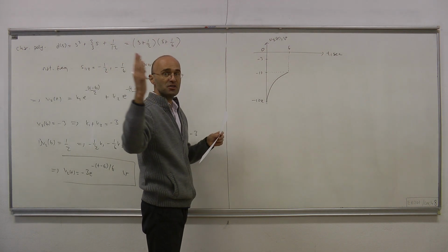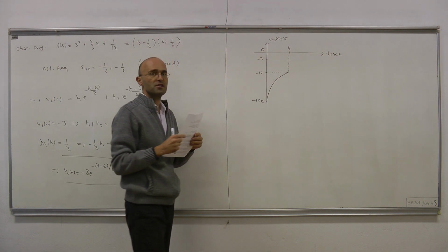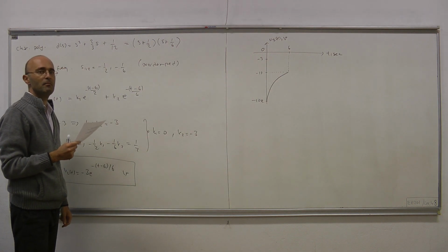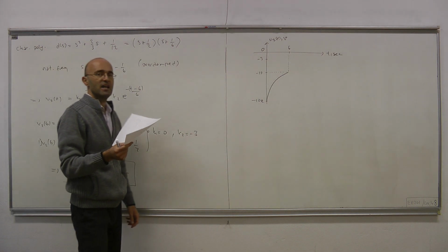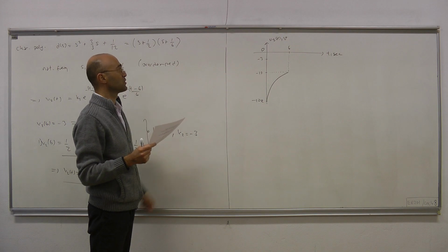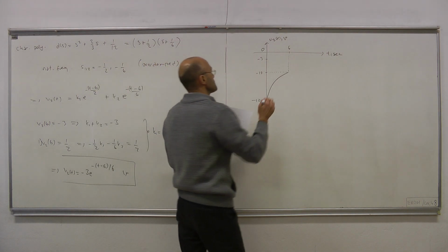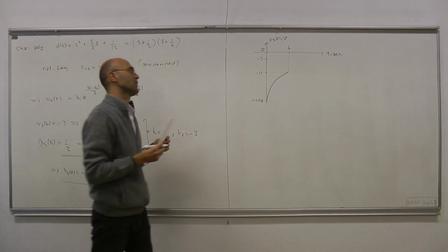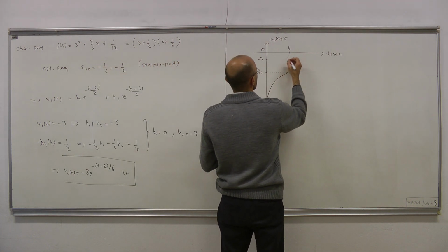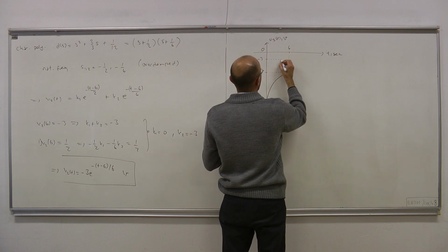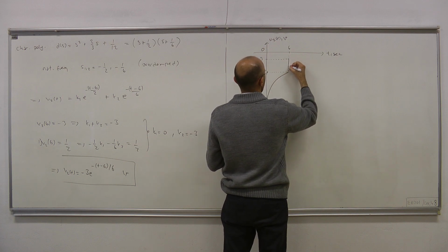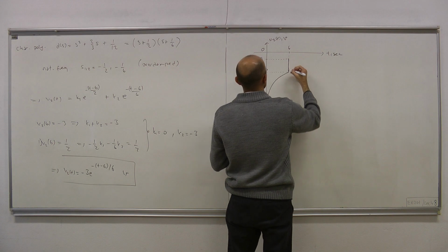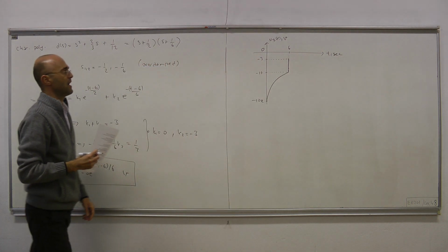Okay. And then at that instant, the switch changes location, forces the two capacitors to become parallel. That means by KVL it forces their voltages to become equal, and that results in a drop of 7 volts for the second capacitor voltage. Okay. So we jump to minus 3 from minus 10.